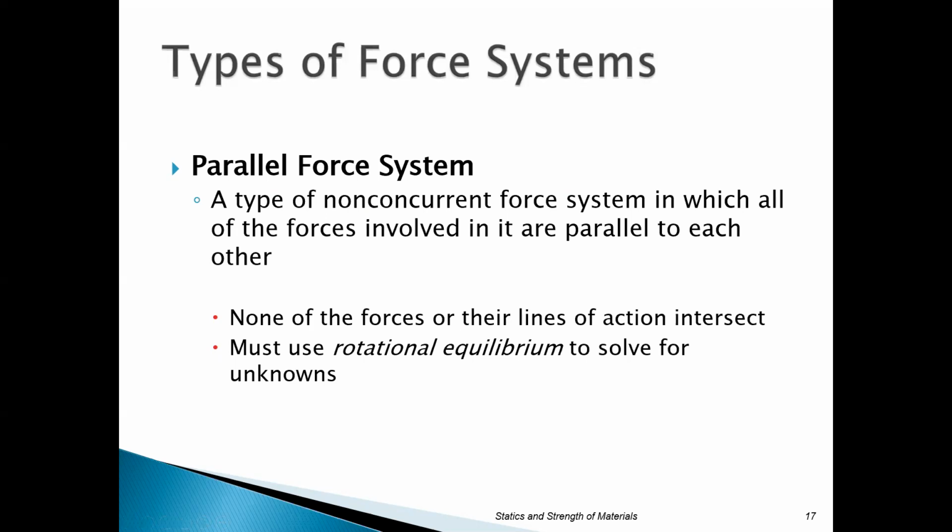And in this case, we're going to have to use what's called rotational equilibrium to solve this. Rotational equilibrium is actually a very simple process, and you're going to find parallel force systems are going to be one of the easiest types to solve. Even, I think, sometimes easier than the concurrent force systems.